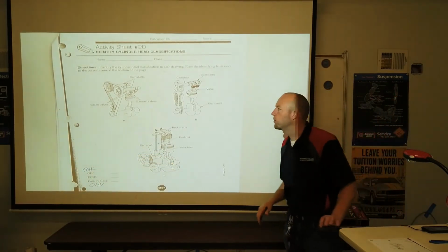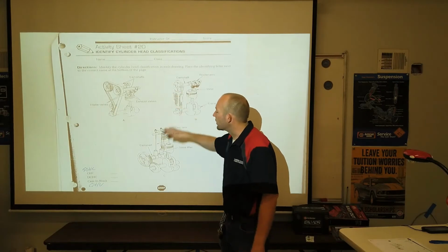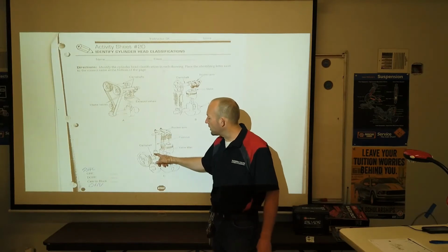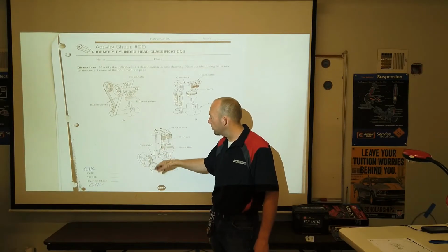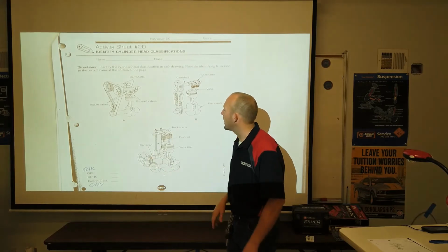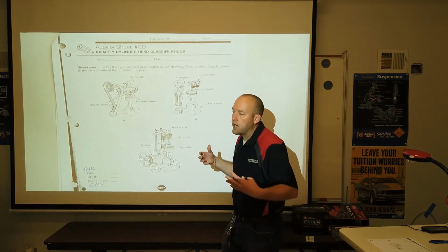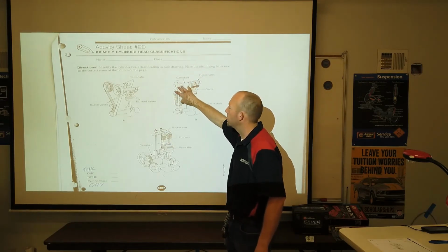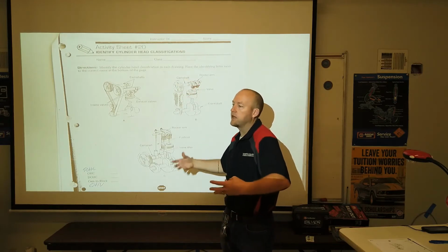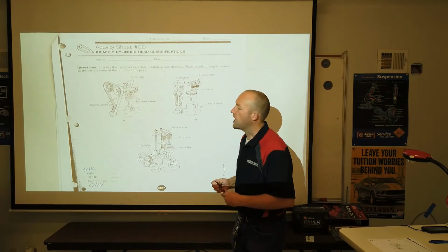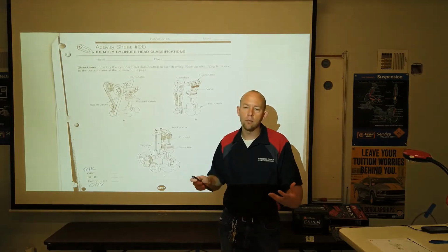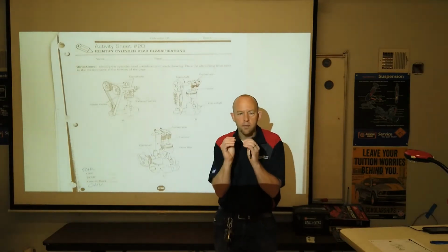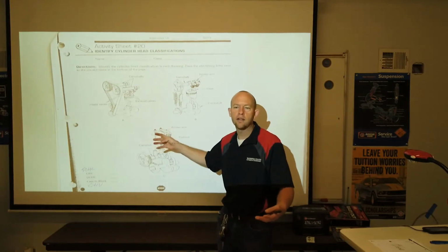So, in this configuration, we have eliminated a lot of the valve train. We've eliminated, in a lot of cases, the push rod. We've eliminated the lifters, and so now we have the cam up overhead, closer to the valves where it would operate them. This is an increase in efficiency and gets rid of weight in the valve train, and it has the effect of making that motor more responsive. Because it's closer to the components it operates, there are also fewer parts to wear out.